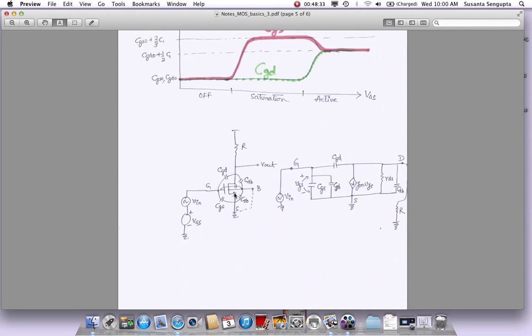So let's see how we change the model now. Here is the MOS device, which had no parasitic capacitance. It was our simple NMOS amplifier with a resistive load. So how has it changed? Now we have put a few capacitors from gate to source. We have put CGS, which is the dominant one, the biggest capacitor. We also have gate to bulk, another capacitance, and since our bulk is the same as source, I've shown it in parallel with this.